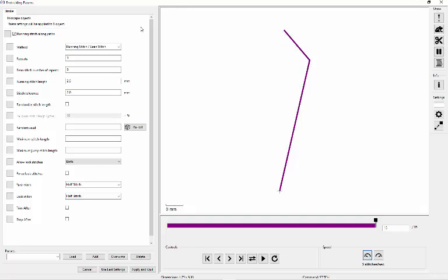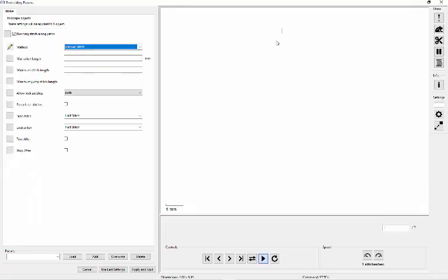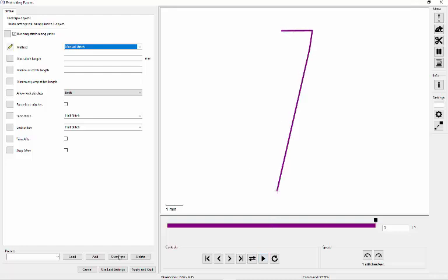Okay. Now, if we change the running stitch to a manual, then it will respect that exact horizontal position, and that's really what I prefer on running stitches. I prefer the running stitches to run as a manual stitch. Now, one of the drawbacks in doing that is, let's look at our needle points.